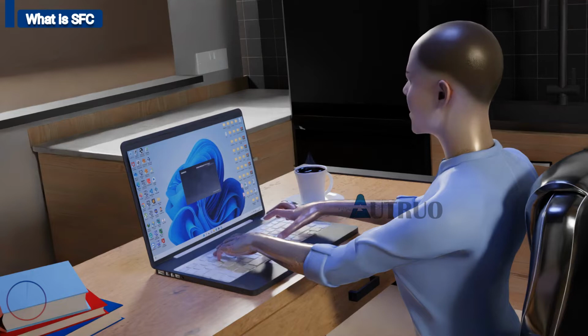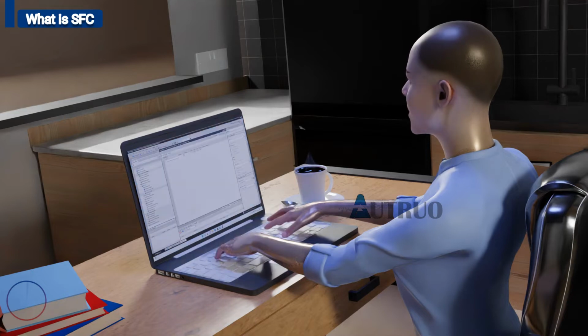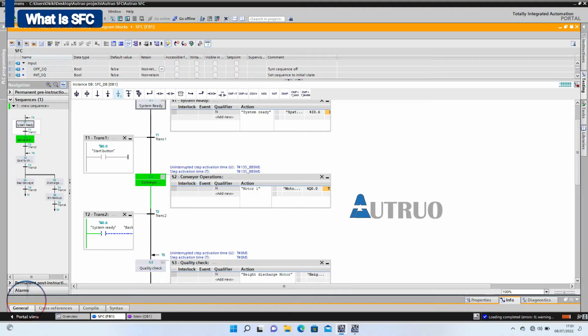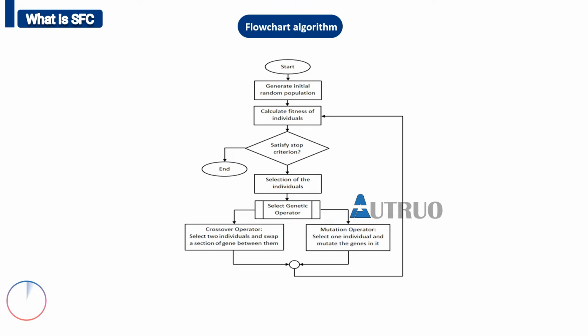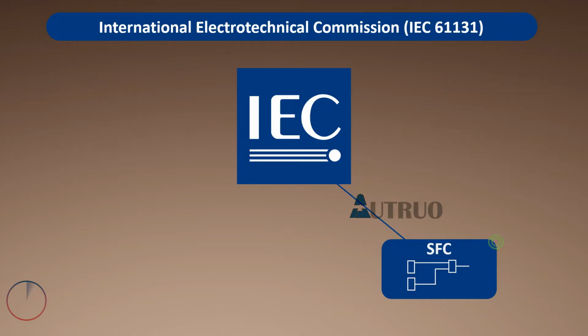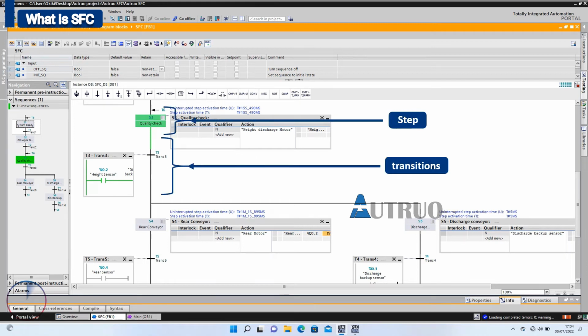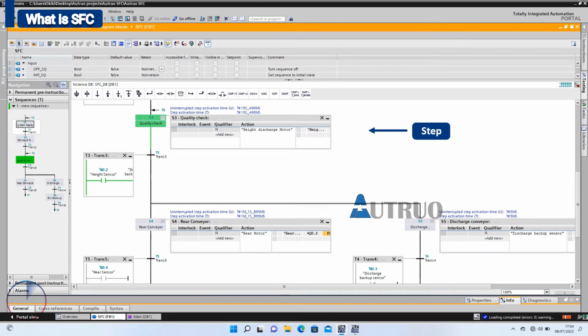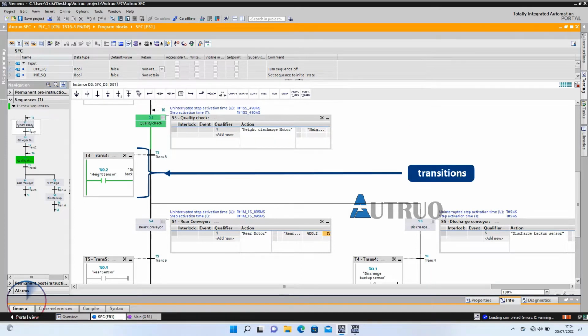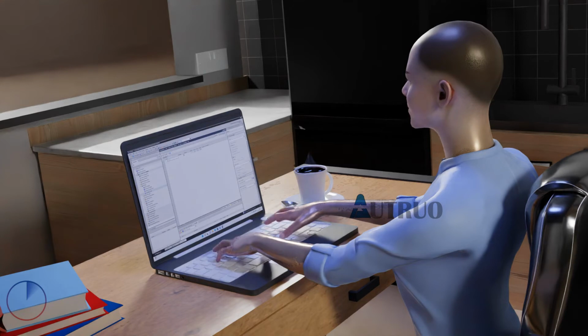Sequential function chart is also another graphical way of programming PLC. This programming language is commonly used and easier to represent scenarios where there are multiple states of operations. This language is also similar to the flow charts of computer science algorithms. However, unlike the other graphical programming languages, sequential function chart programming is done in two specific formats, which are steps and transitions. Step depicts what is happening as per the program requirements, while transitions are the conditions for the next step. Now let's look at a typical work example.